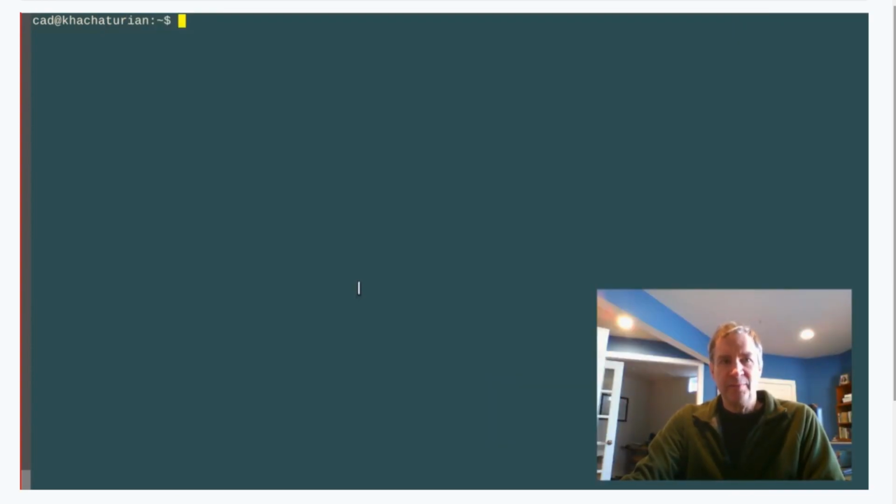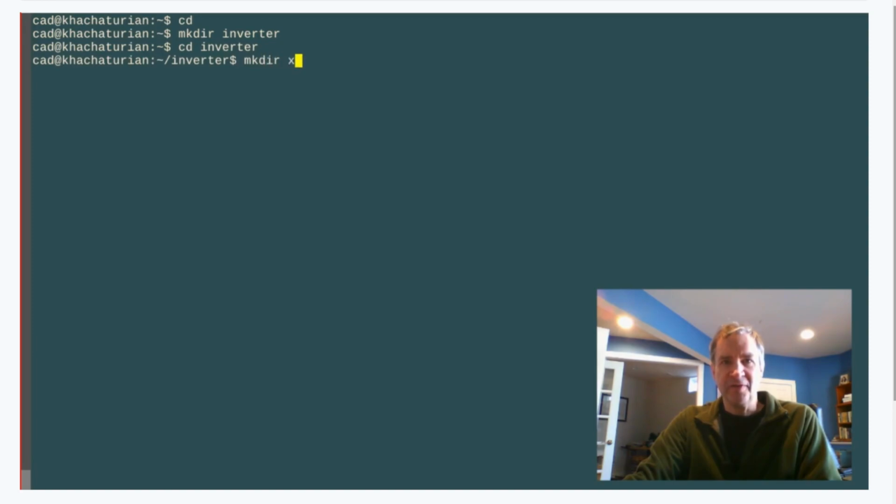We'll start with a simple circuit with just a few devices and no hierarchy as a warm-up exercise. First, go to your home directory. Then create a project. We'll do just about the simplest thing possible, which is to create an inverter. So let's first make a directory for the project, and we'll call it inverter. For OpenPDK's compliance, the preferred method is to have a directory for each tool, so do the following: cd inverter and mkdir xschem, mkdir mag, and mkdir netgen.